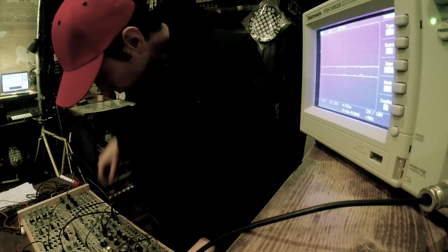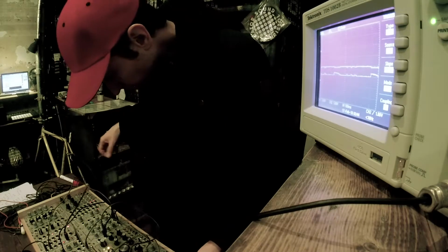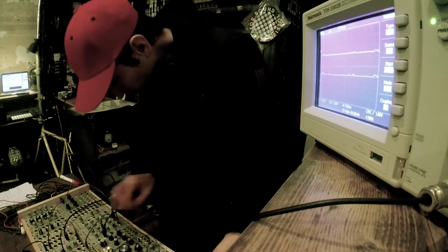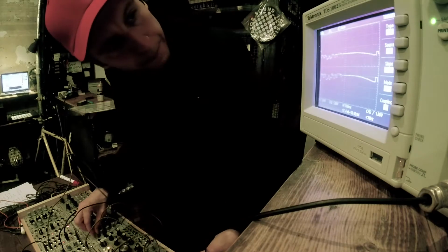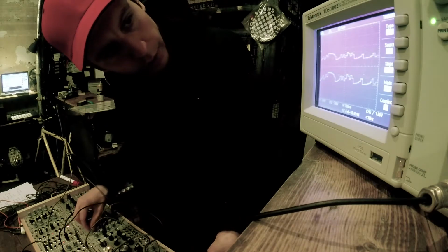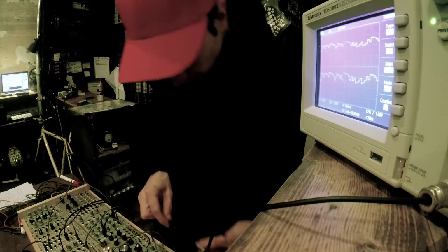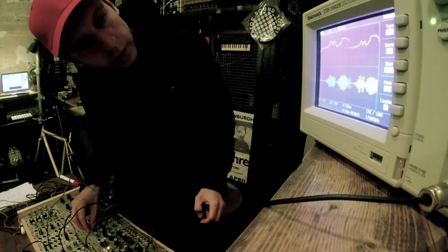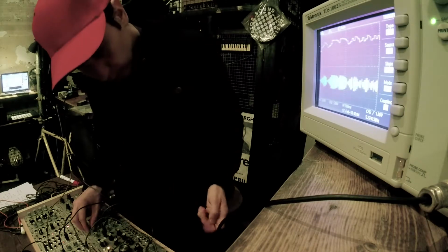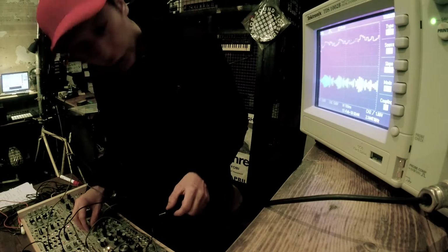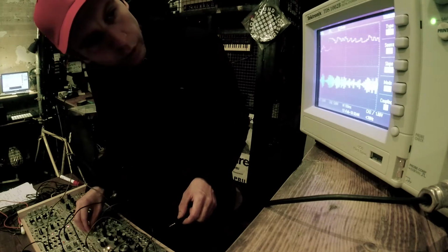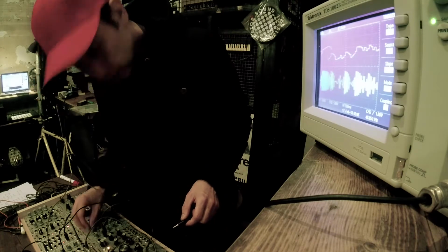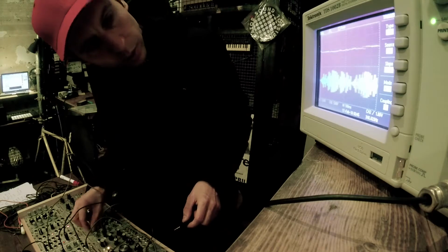That's the output of that in there. Okay, so this would be my threshold. I'm getting into a fairly complex thing here, kind of losing it, because I have two scaling and offsetting stages. Okay, here we go. So we get a changing of the amplitude in there as well. This is the offset, this would be the gain.